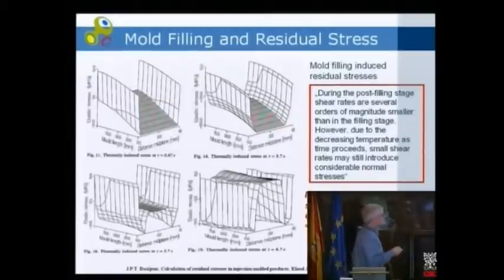And in the end, you have a very strange behavior. You have a compressive stress at the outside, then you have a region of tensile stress and have a compressive stress in the inside. And if you go from here to there, the stresses are very high. They are about 15 megapascal, which is a lot for a green component.